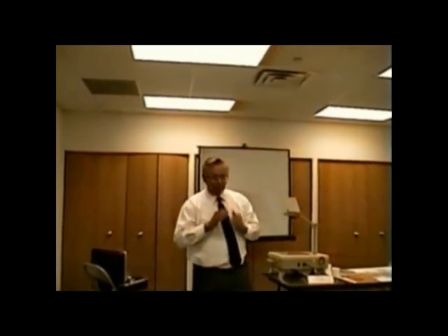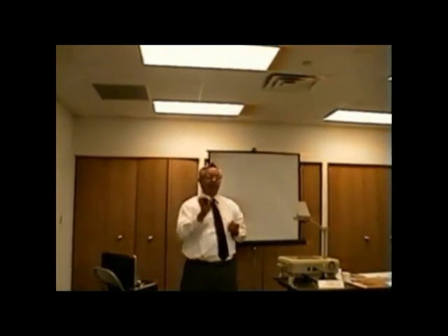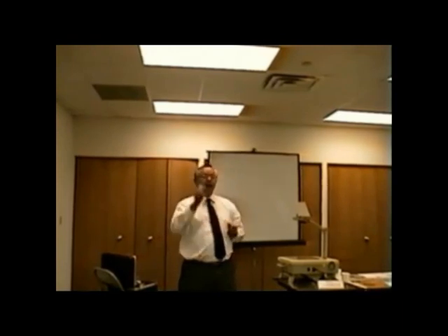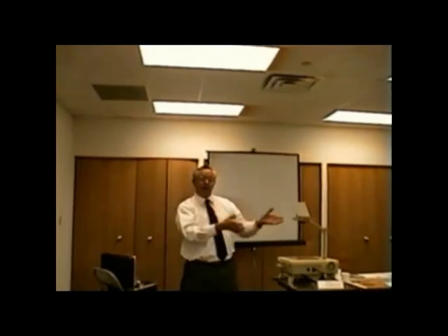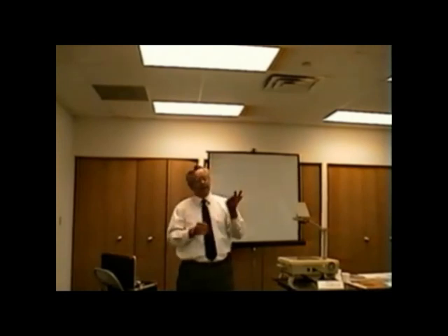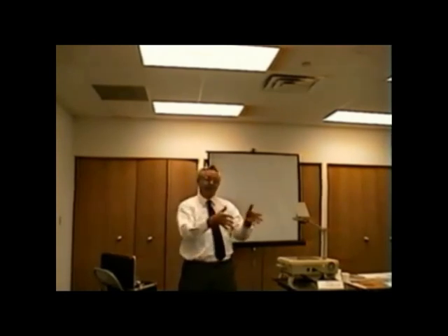And at the same token, this is the part of the class where we also talk about your annual PM check. An annual PM check includes cleaning the flame rod. Ladies and gentlemen, if you talk to 5 people, you get 5 different opinions. I've talked to the manufacturers. We clean a flame rod with steel wool. We take clean steel wool and we clean it. It takes you longer to remove the flame rod from the burner area. You take that out and you clean it and you put it right back, but it takes you a few minutes to do that.